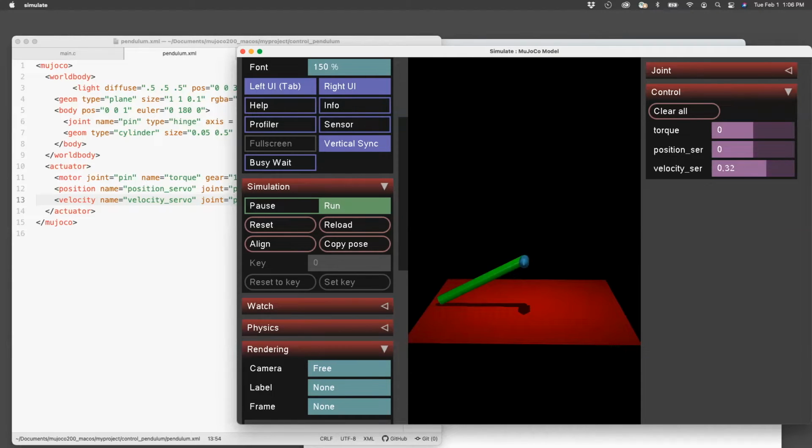Okay, so another problem with this is we have collision zones, and so it's going to hit that floor. So what we can do is we can turn collisions off, and there's an option to do that, but that will still make it this unpleasant thing that will go through the floor, and that won't look good. So instead of doing that, we'll just move the hinge joint up by, I don't know, 1 meter or something like that, and then it will probably not collide with the wall.